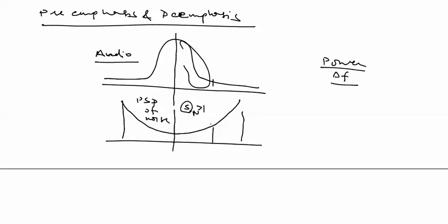For higher frequency, a particular frequency, I mark here F. From that frequency, SNR is lower than 1. If SNR is lower than 1, then demodulation is not proper, not possible. To make it possible for higher frequencies, we have to magnify the signal strength of higher frequencies before modulation.